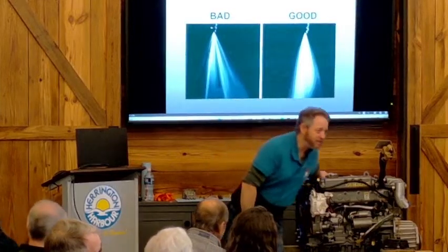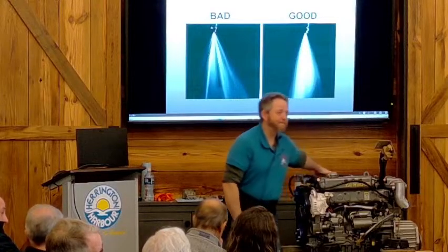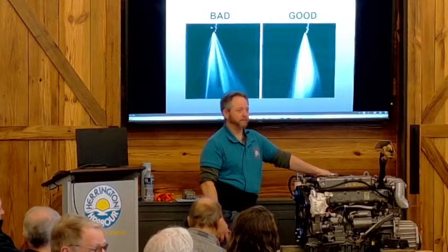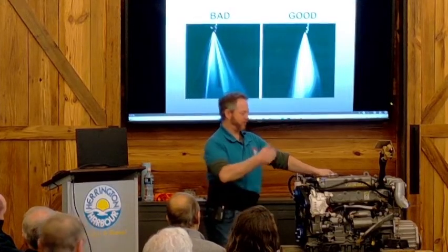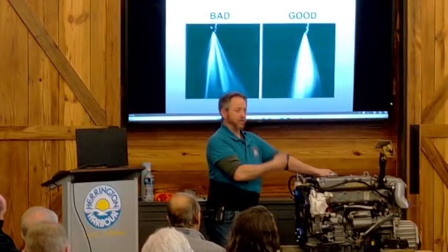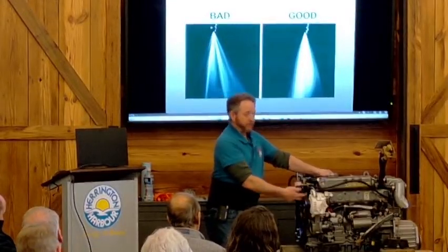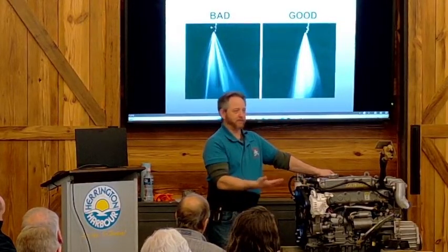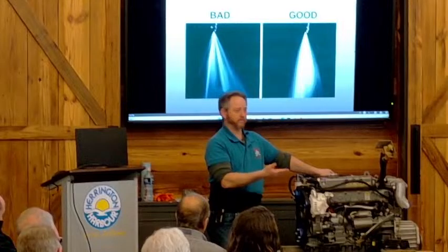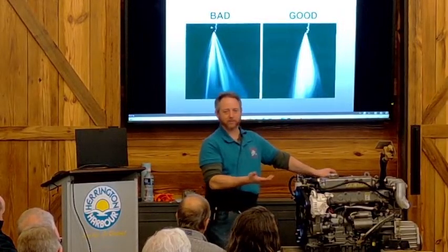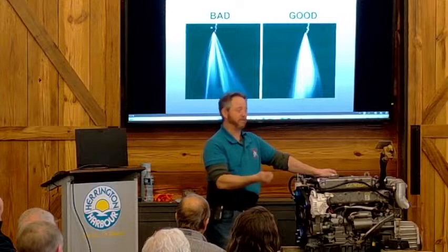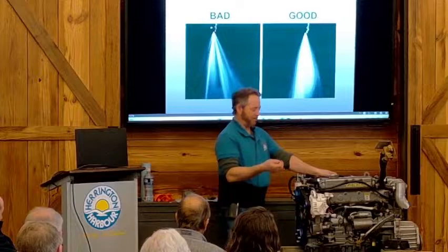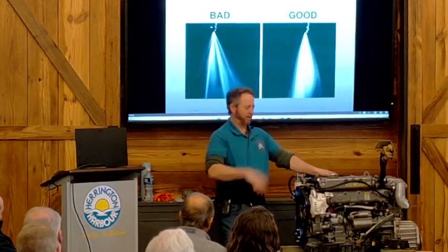What's the yearly maintenance? Okay, the seasonal stuff is going to be changing your oil, changing your fuel filters, checking your belts, checking your air filters, replacing them as necessary. If you have the zinc anodes, or we don't call them zinc anymore because they don't always use zinc. Sometimes they're magnesium, sometimes they're aluminum. So now we call them anodes. So you check and replace your anodes.